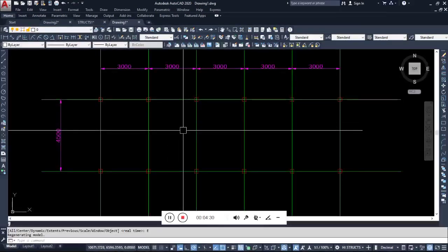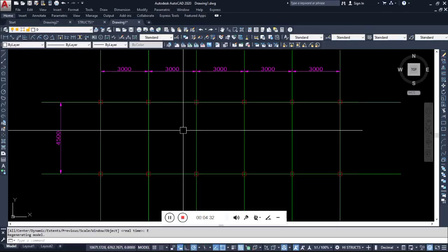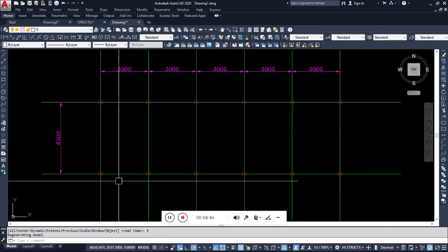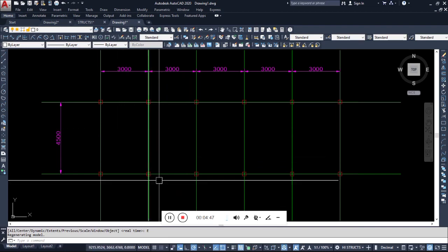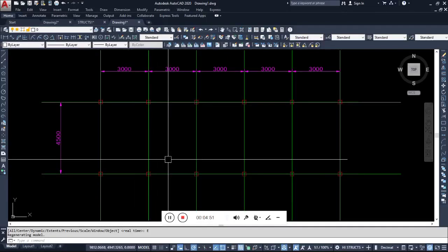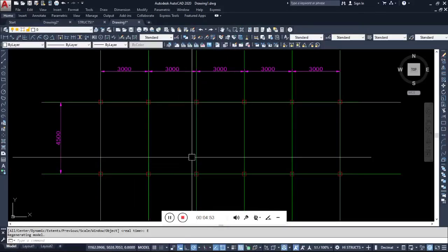Recall that space bar and enter do the same work on AutoCAD. If you are using AutoCAD, I would love you to use your left hand on the space bar, your thumb on the space bar, doing the typing, while your right hand is already on the mouse. It's better to use the space bar as your enter, so you can always type.